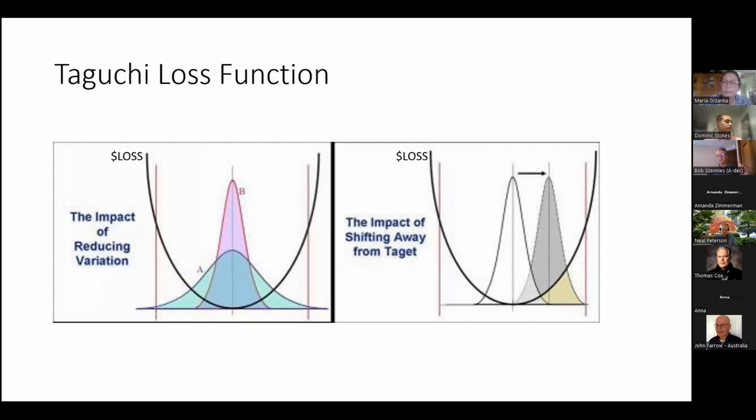Your long-term target can be lower, can be 3 minutes or 2.5. Right now, we're just trying to gain control and be stable somewhere. In process control, that's not unusual at all. We're trying to run here at 12 right now, even though we know best would be 10. That's okay. We'll get there, but we've got to get some stability first. Then when we know how to make it stable, we'll shift it down to 10. I don't know if that helps.